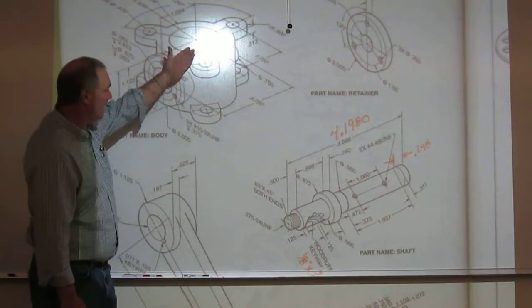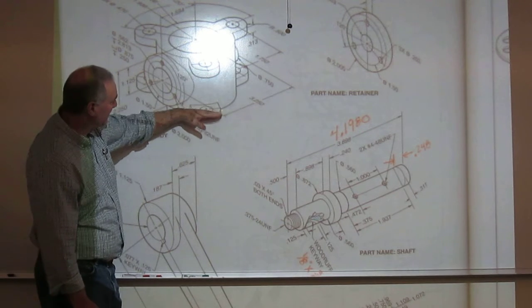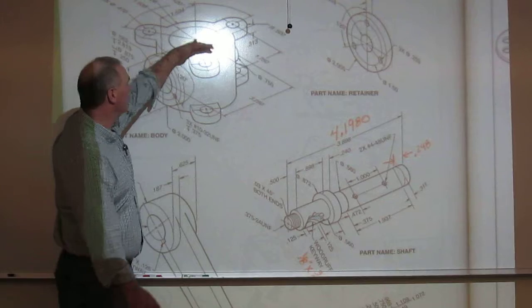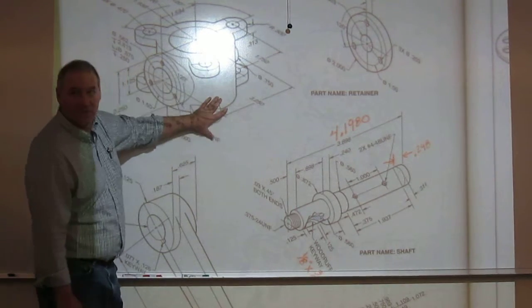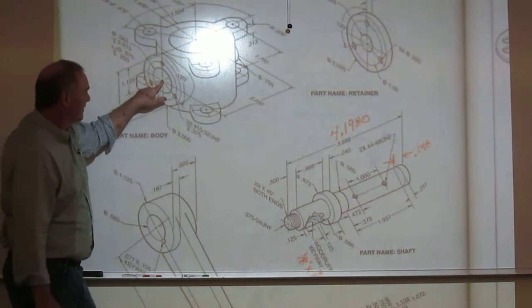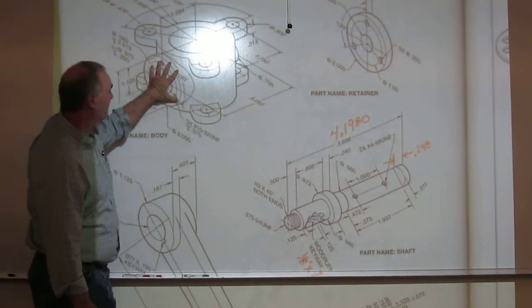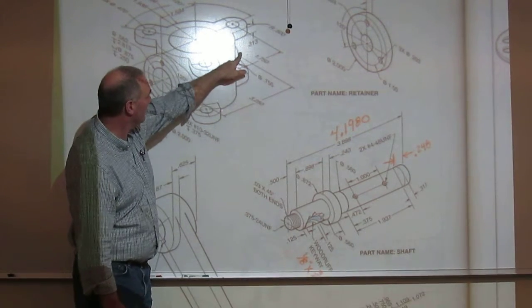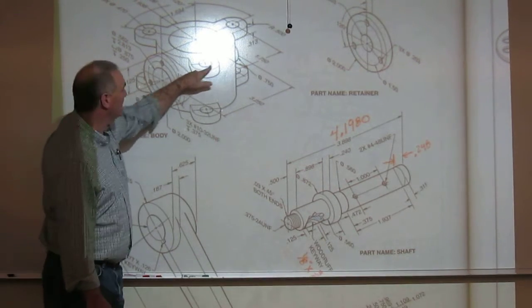Now, I do have a height datum that goes along with that, in that I have this little piece that comes up 0.3 inches, I have this piece that comes down 0.3 inches, but this is the datum I can use to control all of that. I have one other datum, and it's this center line. Everything around this circle center and that little boss at the end, they're all on this center line.